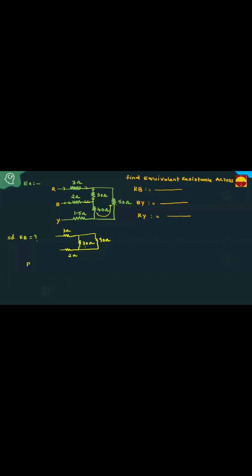Now what is the RB, students? 3 plus 90 into 30 by 90 plus 30 plus 2. Then how much can you get? That is 2700 by 120 plus 2. This is approximately equal to 27.5 ohms. Is it correct? 27.5 ohms. This is RB. Clear, students? That is how to answer.